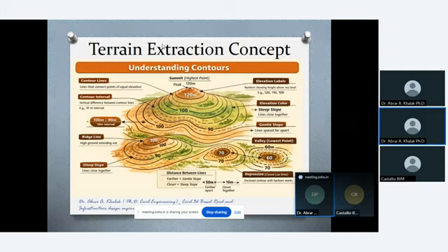Then you see the summit. This is the highest point of the terrain. See the middle of the image, the summit, the highest point of the terrain, and closed circles with increasing values show a hill. Example, you can see 90, 100, 110, 120, this type of points in the image. So the center is the highest point, which is known as a summit.